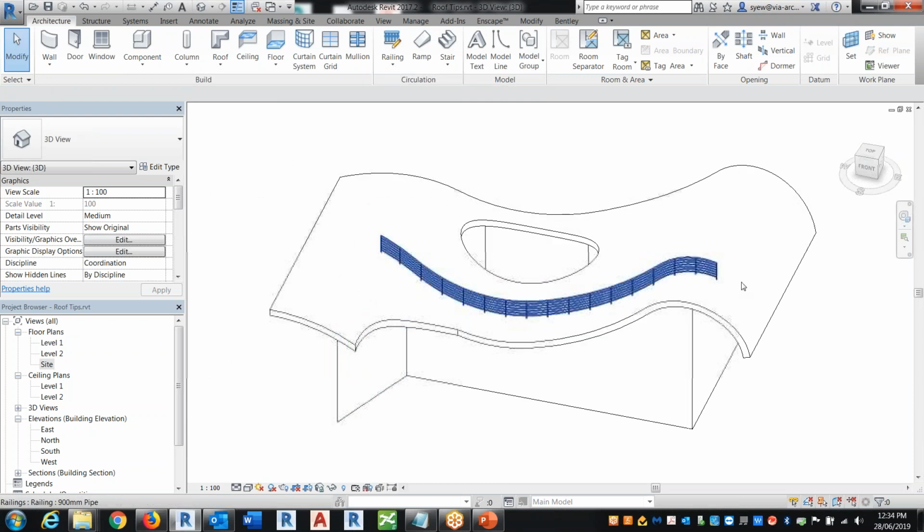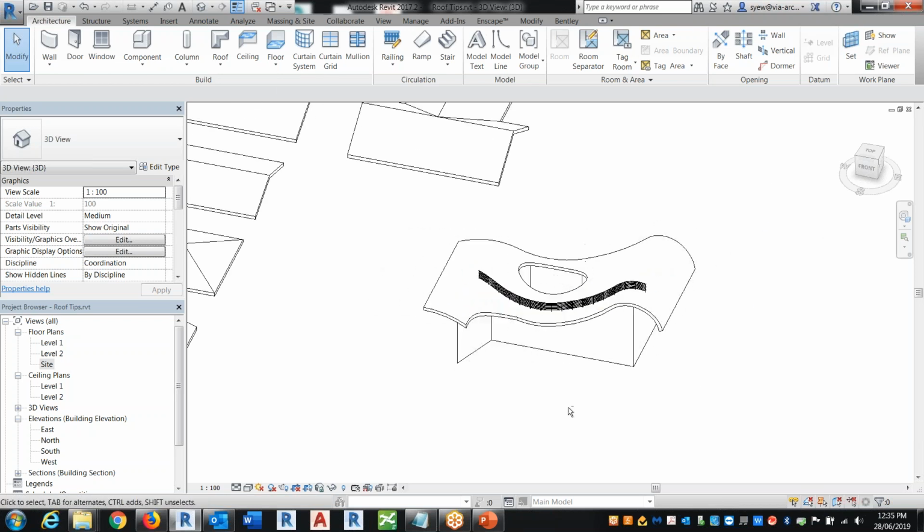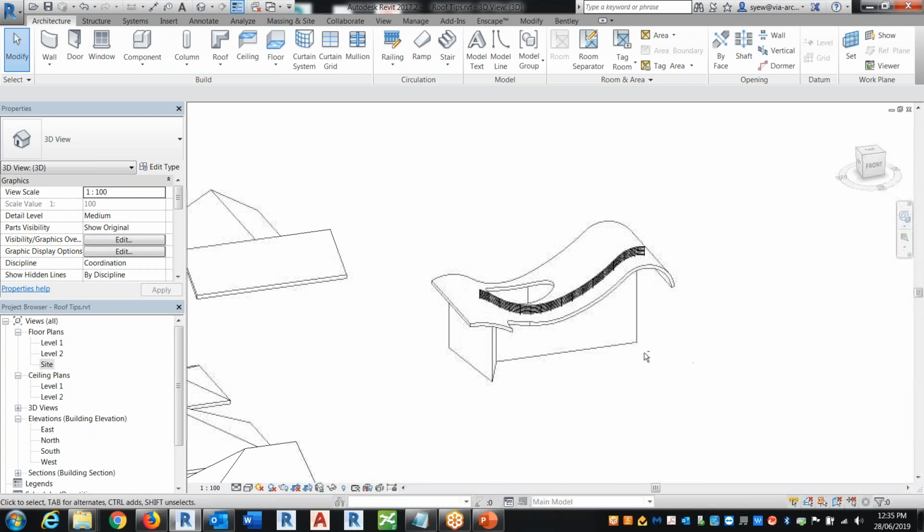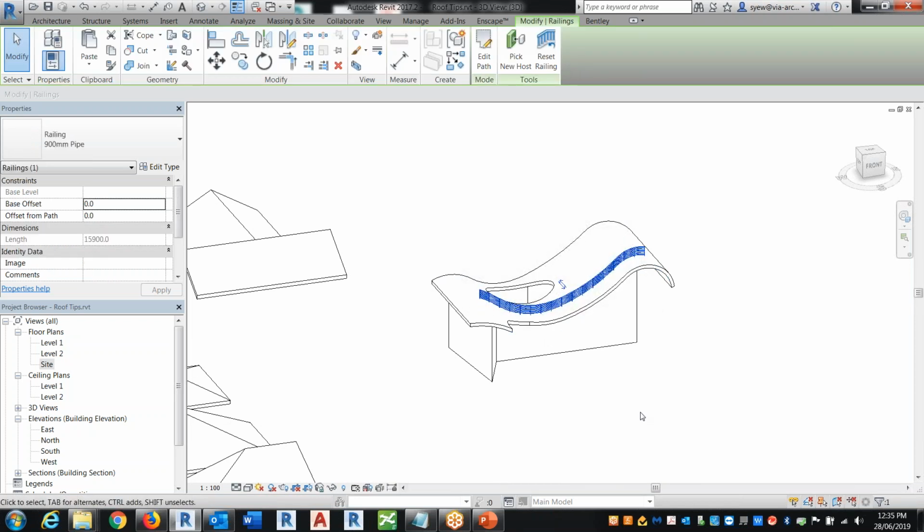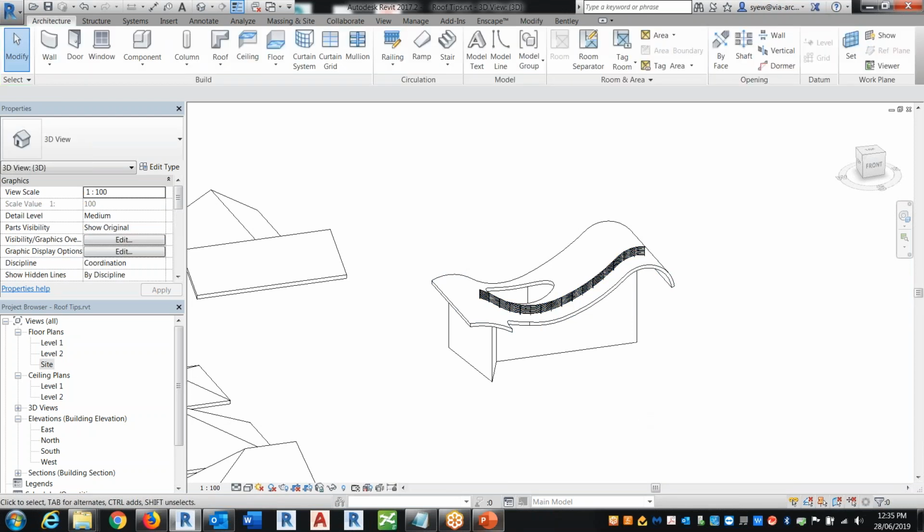So what you can do is actually draw a parapet and stuff like that, or a guardrail. You can do a really funky shape with railing, and then what you tell Revit is to just host it to a roof, and then it will create these curvature surfaces. I think that's something new in 2017. I don't think in 2016 you can do it. Okay, so yeah, that's the nicest thing. You can actually build your curbs and stuff like that. Let's say you have special planters you want to build, like a slope wall, and you want to do this. Yeah, this is perfectly fine.